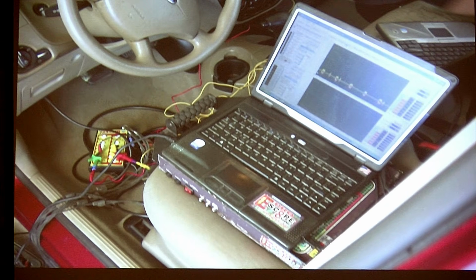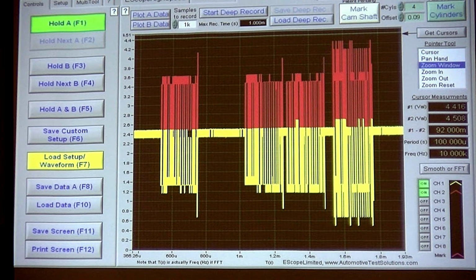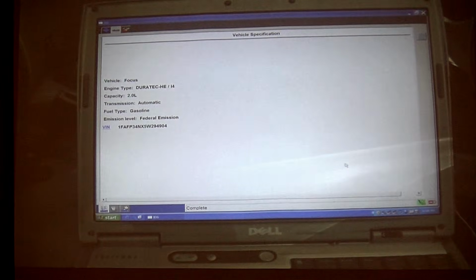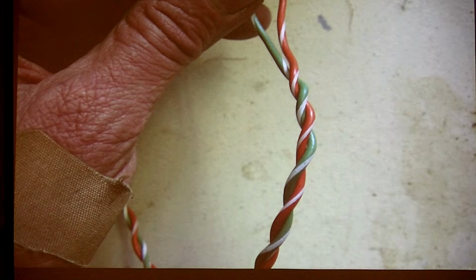Here I've bridged the system. Did I fix it? Yes, because it's not ringing. Why did it ring? Because I've lost the termination resistors with more than 2 modules on the bus. That's what happened here. So basically now I can get the data. I've got the car. I'm going to spin my wires.